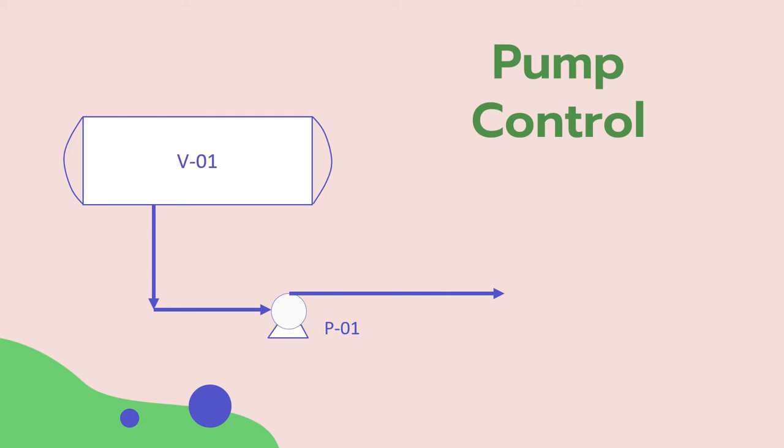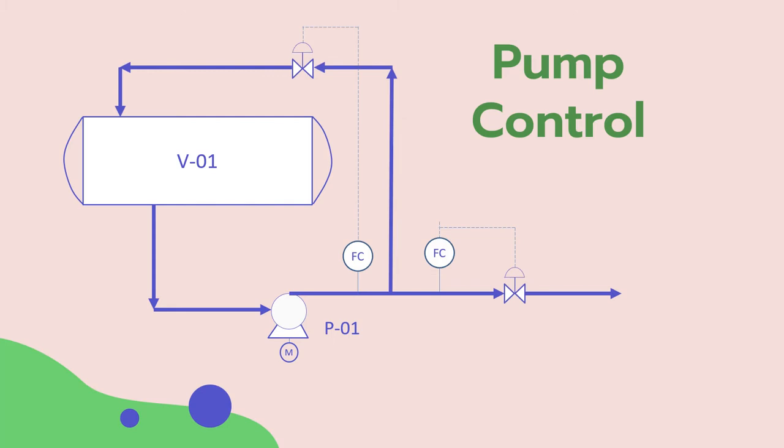We may also use a variable speed control to reduce the motor speed, hence changing the pump performance curve. Or the most common form can be through controlling the pump capacity, by placing a control valve on pump discharge to control the system resistance.